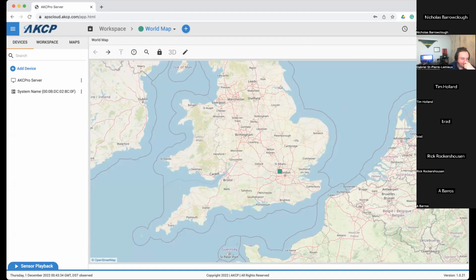Where sensorCFD comes in is where we take real life sensor data and constrain that model using real life sensor data rather than arbitrary numbers. The arbitrary numbers give you an indication as to how your data center should be performing, but the real life sensor data will give you what's actually going on.